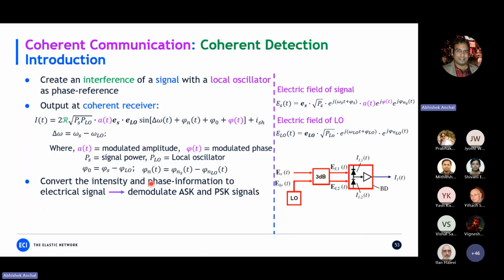To overcome all these problems: first, it allows only differential detection; second, it can't demodulate square higher order modulation; and third, the sensitivity is very low. We move to coherent detection. So those are the very early era of detection of symbols. After that, we move to coherent detection.